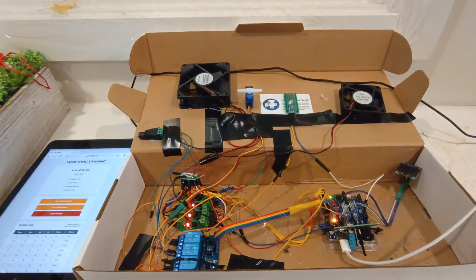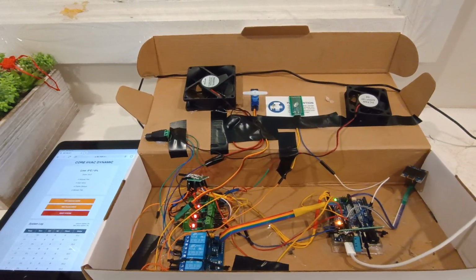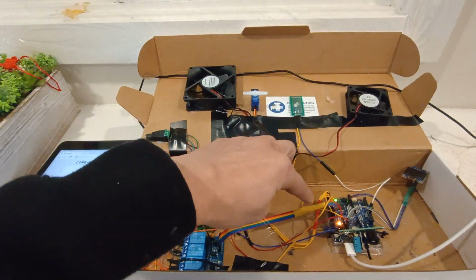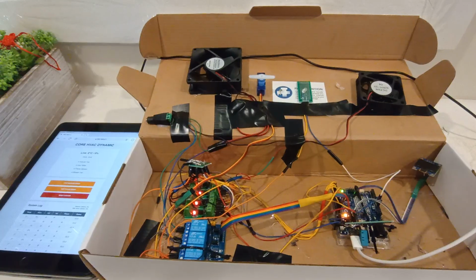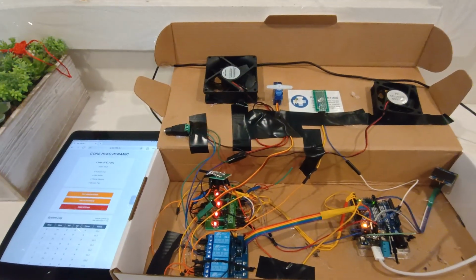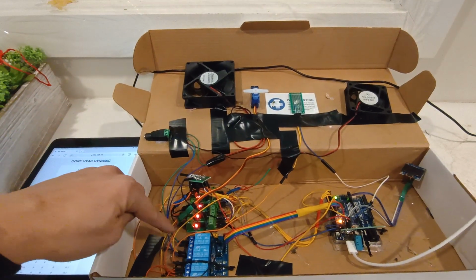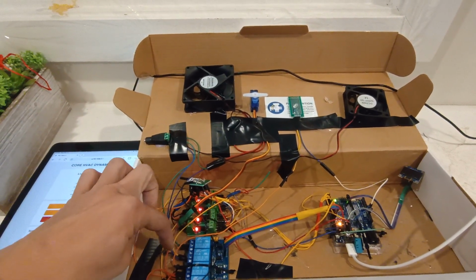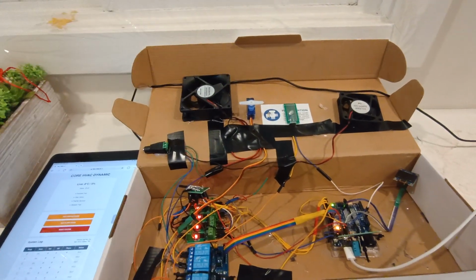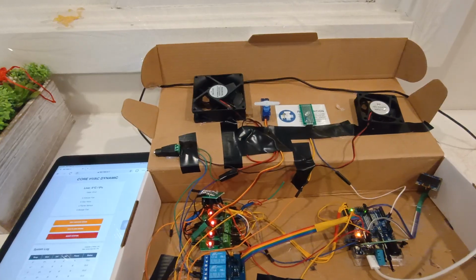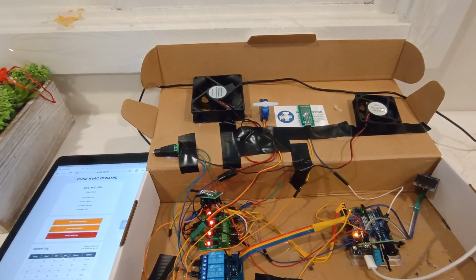When the Arduino board detects the signal, it's going to send the output signal to the relay here to trigger the device on. Then the power coming from the outside will be connected and sent to the inducer fan, the gas valve, the flame sensor, and the fan blower.